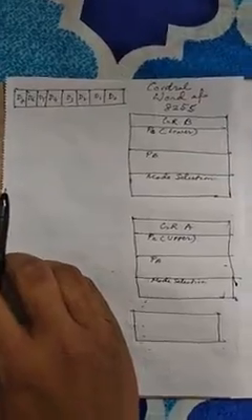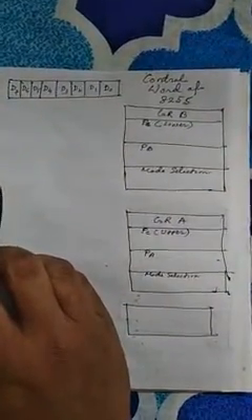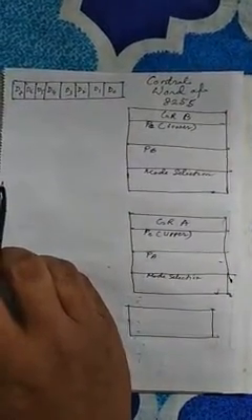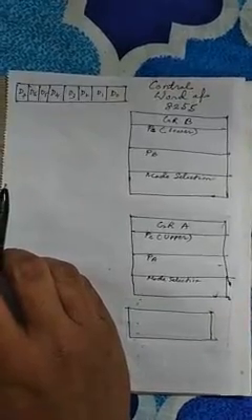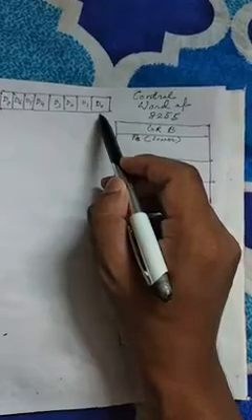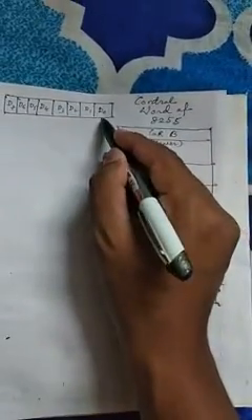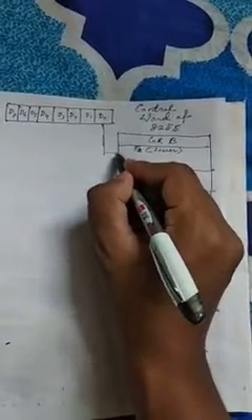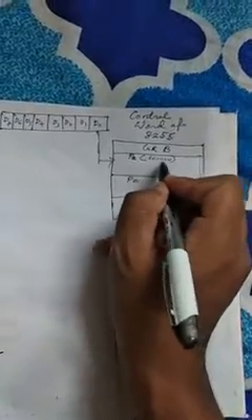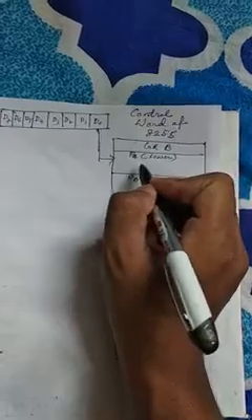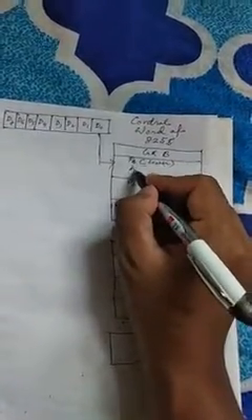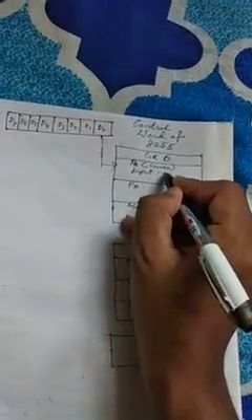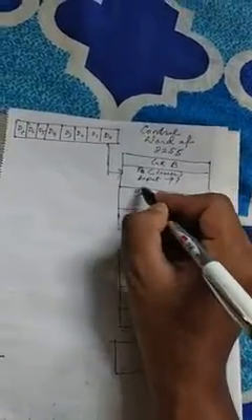Now here in 8255A we have a data pattern of control word. D0 basically specifies whether port C lower can be used as input or output. If it is used as input, then the D0 pattern will be 1.